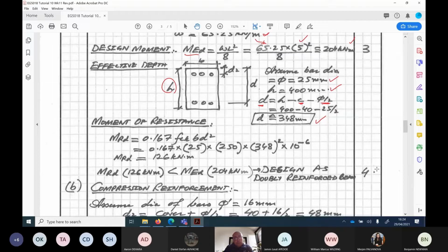Concrete will always need tension reinforcement, because below the neutral axis, this portion is not taking any tension at all. Yes, I accept that moment of resistance is sufficient, but that is sufficient in the concrete part, in the compression part. So the compression part is the top part. So that is strong in compression. It doesn't need any compression reinforcement. That is the meaning.